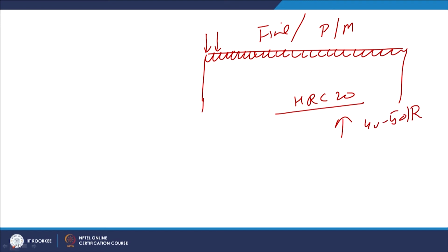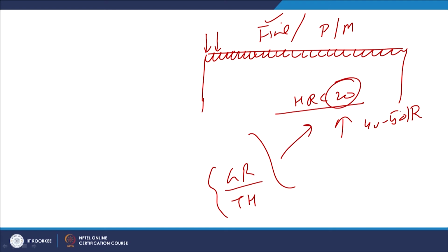So, the remelting using laser or electron beam or TIG of medium carbon steel, high carbon steel or alloy steel will lead to the formation of a fine grained pearlite and martensitic structure, so that it will be combining the effect of both grain refinement as well as transformation hardening, and the combination of both these two will lead to a significant increase in the hardness from about 20 HRC to 40 to 50 HRC, and this certainly will improve the wear resistance.